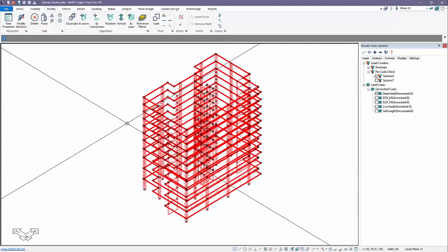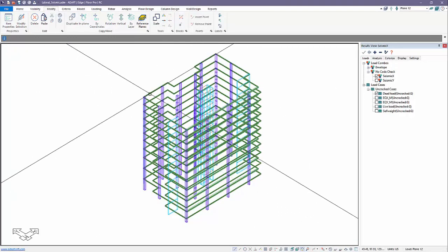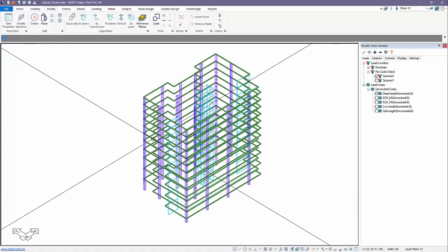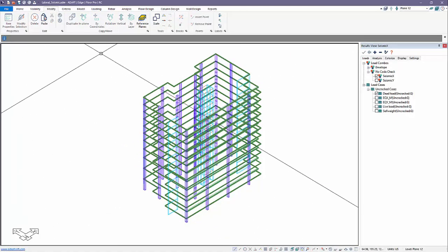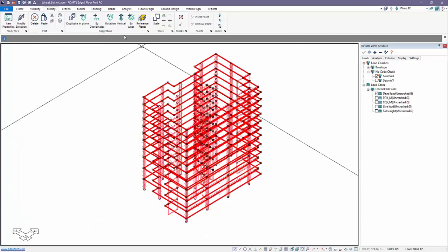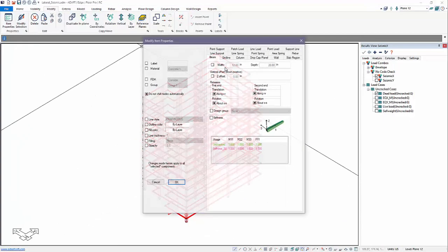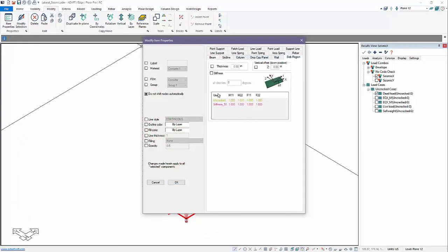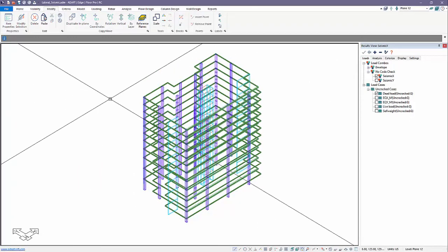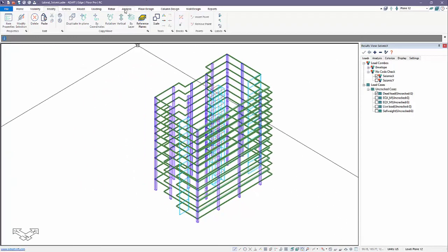And we could do the same for slabs. We'll leave the slabs at 0.5, or excuse me, we'll set the slabs to 0.35. So we'll come back, select everything. Again, repeat the procedure. We'll go back to slabs. Here we're going to set this bending stiffness to 0.35. We'll add a little bit of variety there, even though we said earlier we would not. So we'll add that as 0.35. And now we're going to run the model.